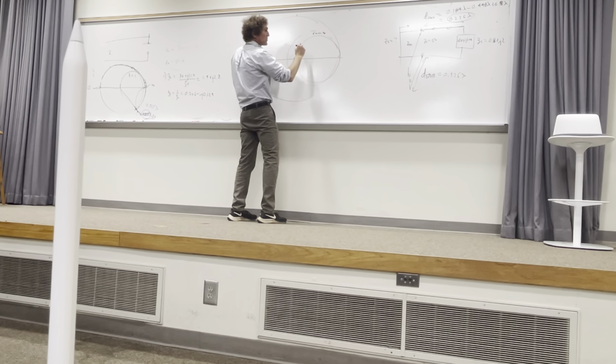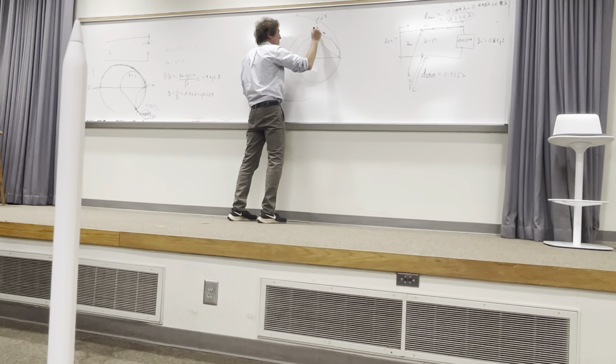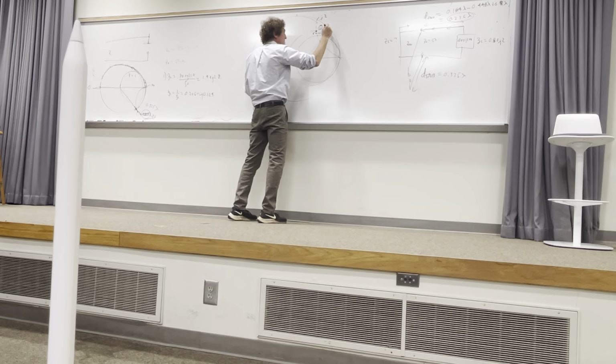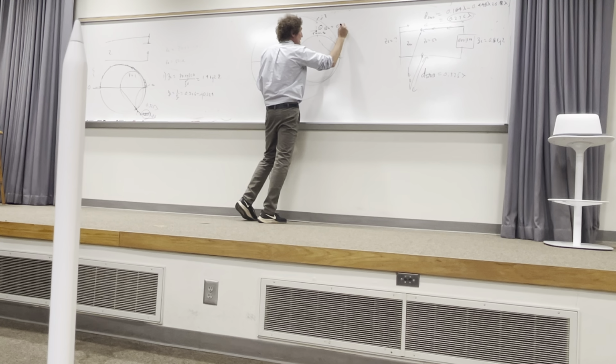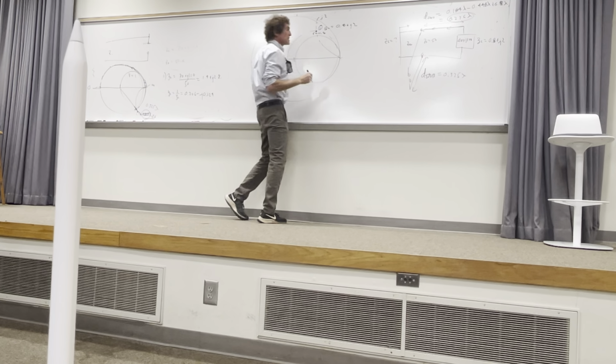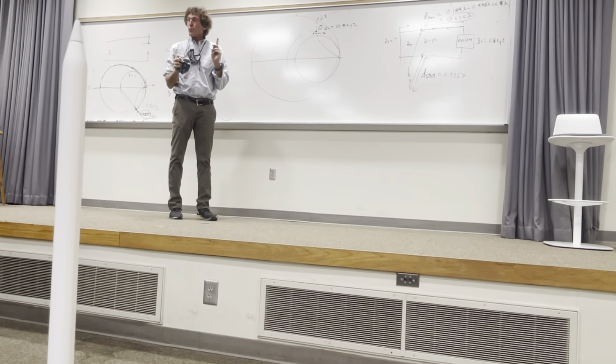And then j2 is right about here. So if you follow this in, this should be your first point, ZL, which is equal to 0.8 plus j2. Can you all see that? Now remember, we attach that shunt stub in parallel, correct, class? Just keep that in mind.